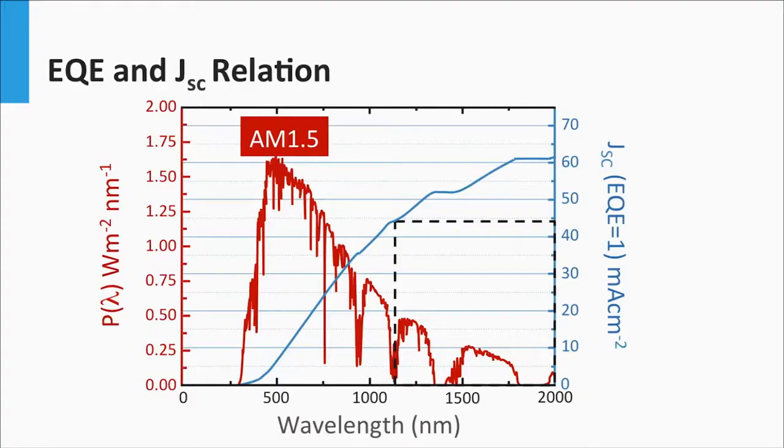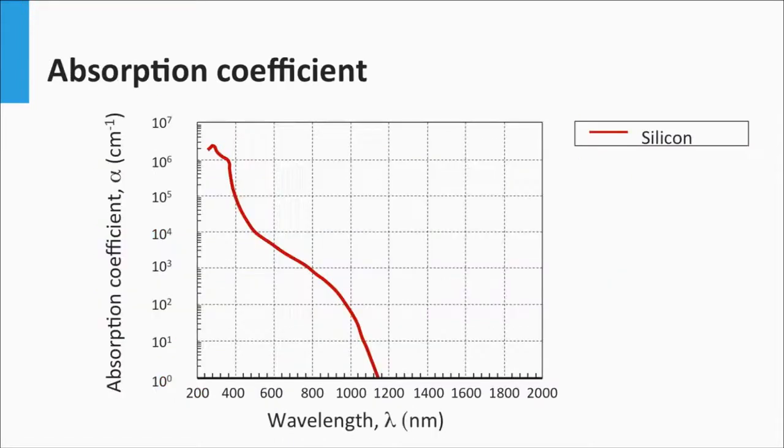Let's consider the design rules for solar cells as introduced in week 3. Let's start with spectral utilization. A band gap of 1.12 electron volts means that in theory we can generate a maximum short circuit current density of 45 milliamps per square centimeter using crystalline silicon.